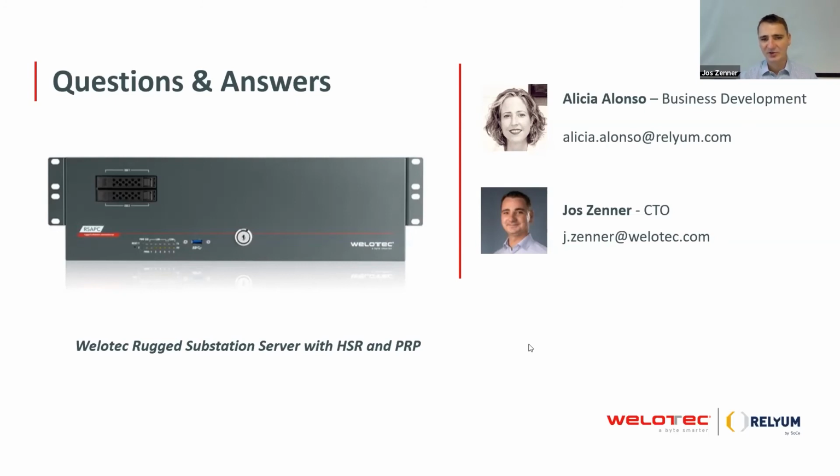Okay, the next one. Can a server configure some logic to use for tripping and control system? If yes, can we utilize it as defense scheme protection system? In general, yes. So for this application, you probably need to pre-process the sample value streams, and then having some software analyzing and doing tripping and control.